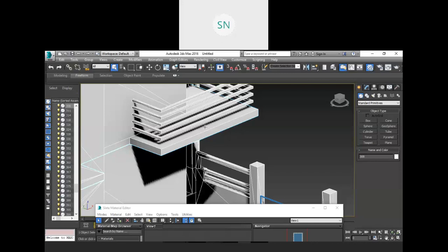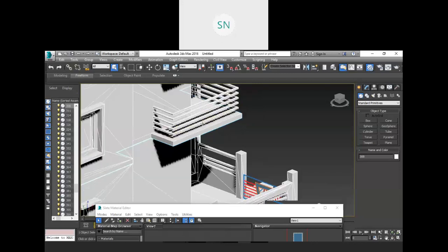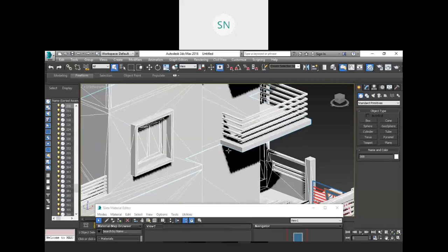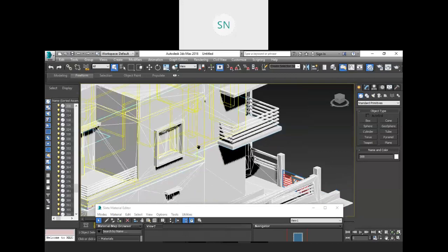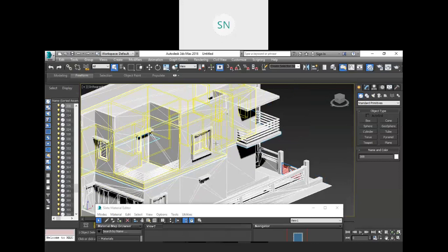So if you have a Revit file and you want to open that CAD model in another software which doesn't support the Revit file format, what you need to do is convert your model into IGS or STEP file format, and then that file will be readable in whatever other software you want. Is it clear now?